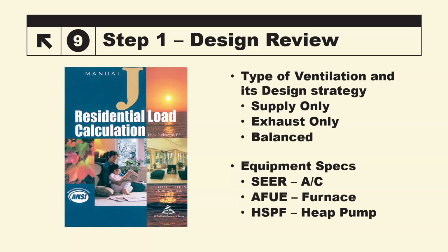We're looking at the efficiencies of that: SEER on the AC side, the AFUE for furnaces, and then, of course, the HSPF for heat pumps. That's all part of the Manual J, just verifying what the specs are that we have.